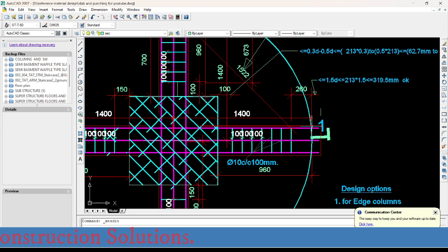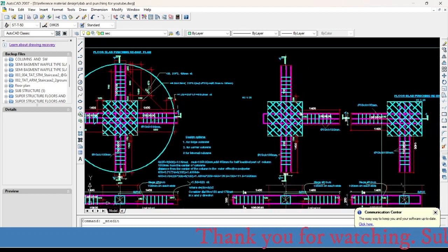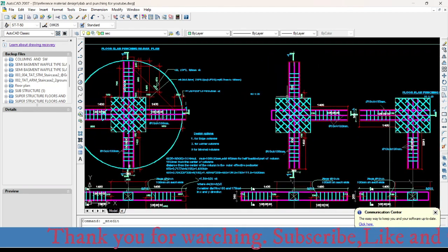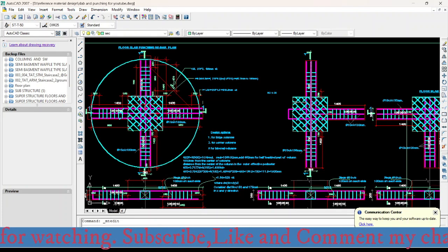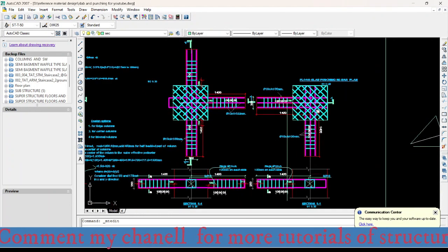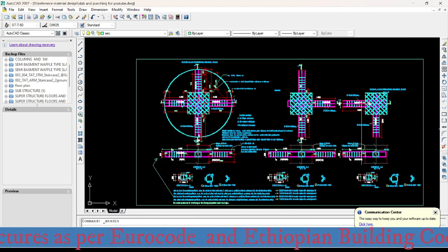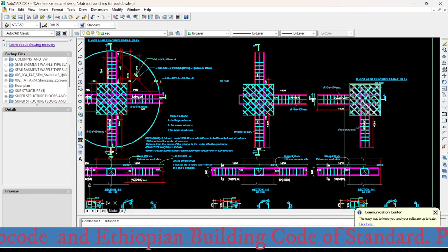This is when we arrange river ties orthogonally for the interior column. For the edge column, we can just replicate this, except excluding this wing. And in the case of the corner column, we can simply use the two orthogonal river sets, this one and this one, or this one and this one, because here we are using the corner column.